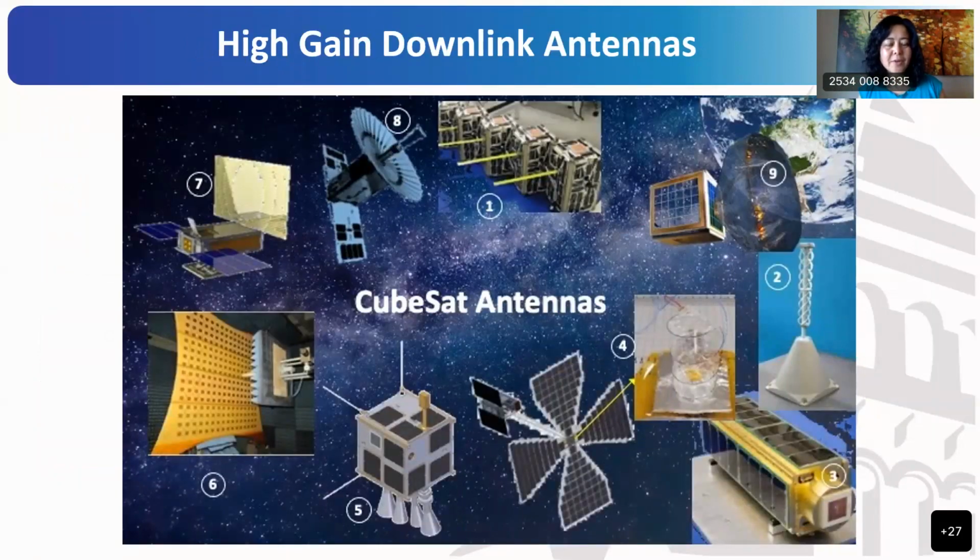Okay, so we talked about 3 types of antennas now. Antennas placed under the solar cells, on top of solar cell, and around the solar cell. All of these are antennas at element level, just one single antenna. We didn't go to the array configuration yet, right? So earlier when I said link budget, I showed you to establish the link from the ground to the satellite, to command the satellite, we need a UHF link. Most often we need a UHF link.